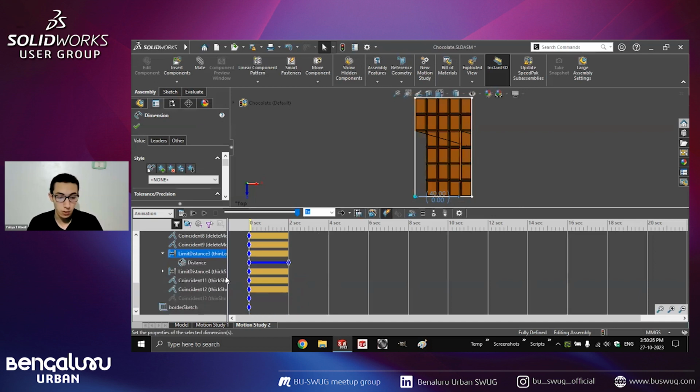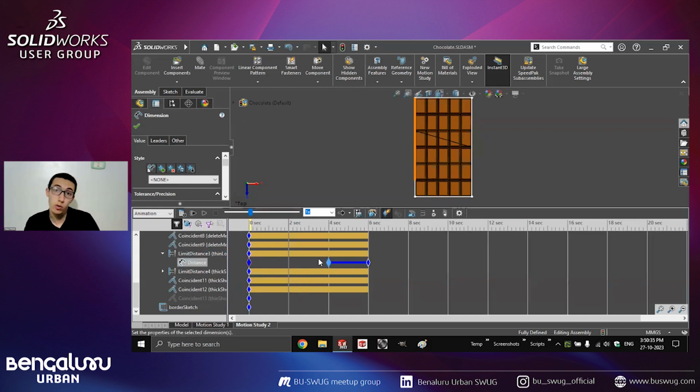So for example, let's get this all the way to 6 seconds. And maybe I just want that change to start after 4 seconds. So if I drag that original key point over here, it's not going to change at all during this time, and after 4 seconds it's going to start to change. You can do anything you want with these key points, but make sure that you're entering values correctly. And if you can use numeric values using mates, that's way better and way more precise than just dragging components by hand. And I can keep doing this on and on.